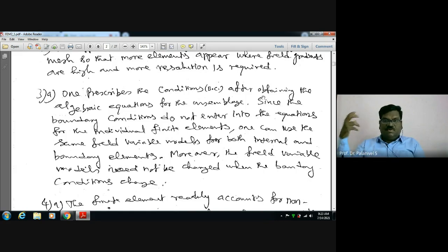You used to play some game, with varying cup, glass and all, some animation. Similar to that is finite element software. Once you have developed the model, suppose you are applying a concentrated load on a particular element. That way the beam is loaded and you are analyzing it. You want to change the load. You have already modeled the beam. You can keep it as it is, and only remove the previous load from the respective element, and apply the new system of loads at the required elements.